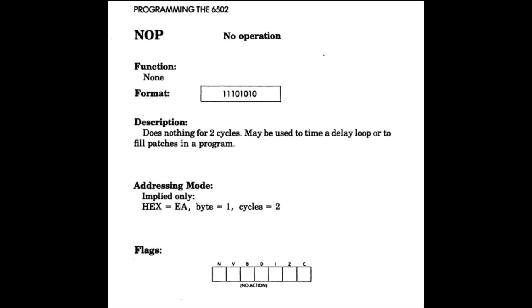Then the CPU will increment the address bus content, read another no operation from the data bus, and cycle incrementing the address bus forever. What happens when it reaches the FF hexadecimal location is that it starts again incrementing from 0. So it will loop through all possible addresses forever, and we could debug the address bus buffers and decoders easily.